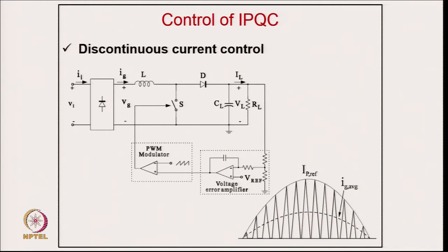at the cost of what? What is the disadvantage? The peak current is much higher, because this is the current which you will get as average current, like typically in the inductor, but the peak current will sometimes be even more than double in this case, because you are missing some period here to make sure of that.